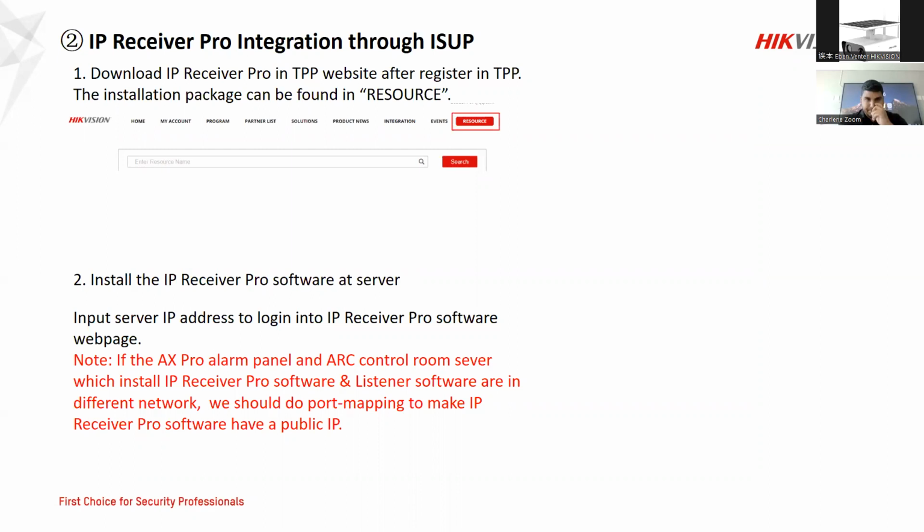We're actually starting to move away from that, for the mere fact that you have to get an external IP address from your ISP, because in order for your alarm system to communicate to your control room, the alarm panel and the security company need to be on the same network. So that's impossible, because a guy stays in Cape Town, for example, and I want my Joburg house to be monitored there. So how do you get it to work?